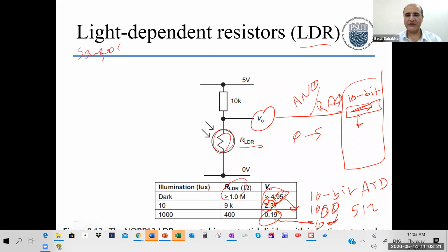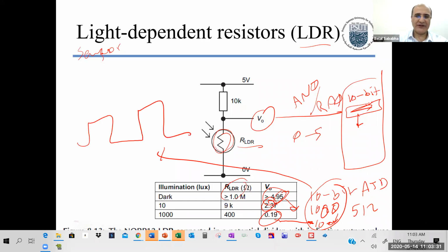it to be fully proportional, you can take this number you read here, convert it. If you have a PWM light, a microcontroller, to turn on the light here, instead of doing a 1 or 0, you can do a PWM, right? And the more time you have the high, the brighter the LED is going to be.